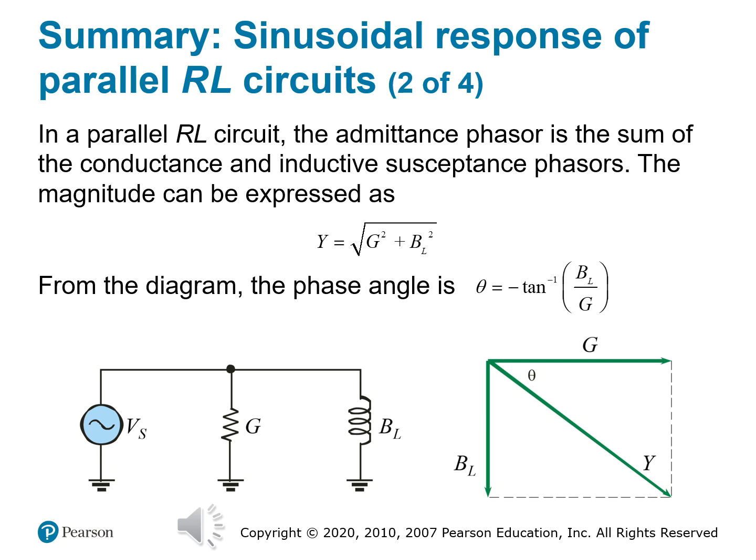And then for the phase angle, theta would be equal to negative inverse tangent of B sub L over G. So the negative sign indicates that the current leads voltage in inductive systems, or from the admittance perspective, current arrives early due to the inductive lag. And this matters because it lets you calculate total admittance just like impedance.